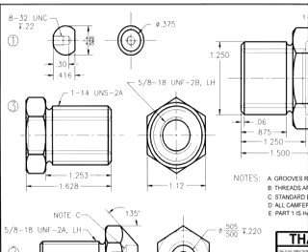Now, you'd think that'd be all, but you'd be sadly mistaken, because there is another specific tolerance on this drawing. Actually, there's several, but they're all the same. And that's this 2 in the 2B, or the 2 in the 2A, or the 2 in the 2A down here. That is the class of fit for the threads to cut. And that is another way of expressing a specific tolerance. So I think we're starting to get a hold of this tolerance thing as far as dimensions go.